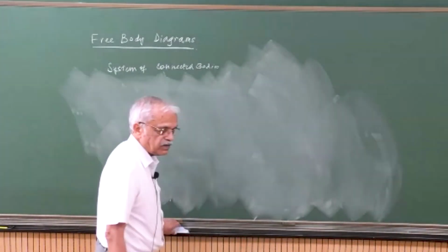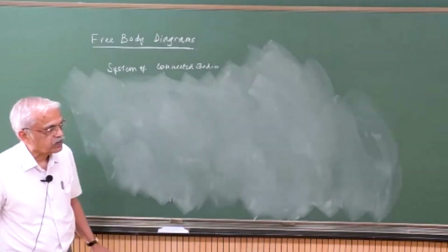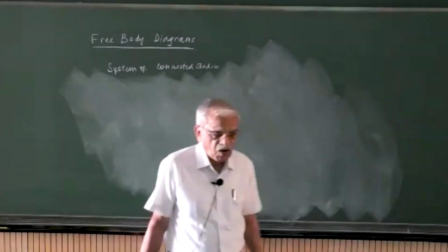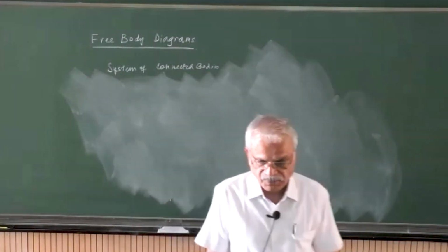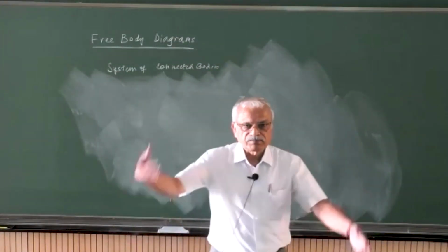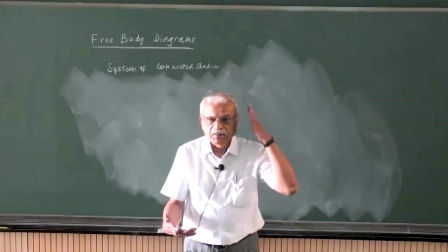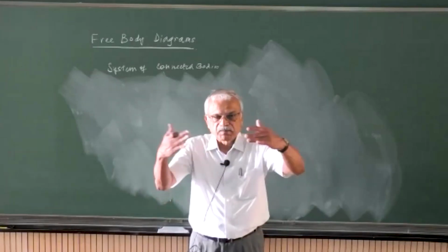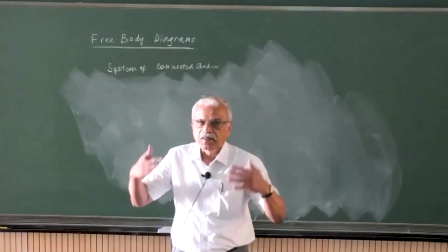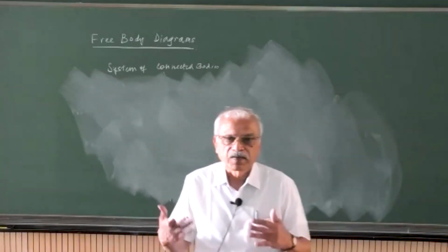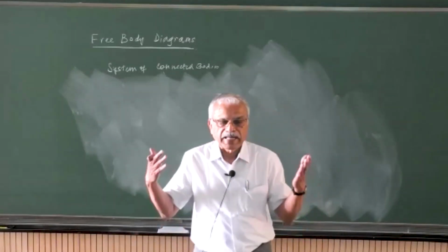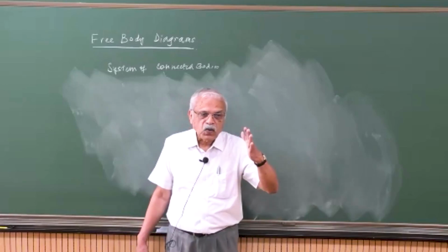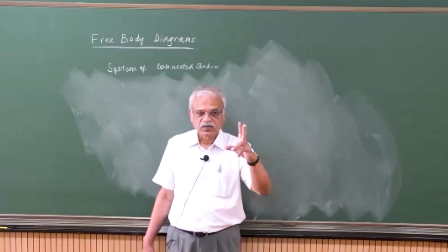There is another very important thing that comes also into picture. We always break at pins or maybe even at the sliding surfaces. Why do we do this? Can anybody say? It's convenient for us, if the bodies are joined by a pin, to break it at the pin because by breaking it at the pin, we are introducing two unknowns, right?